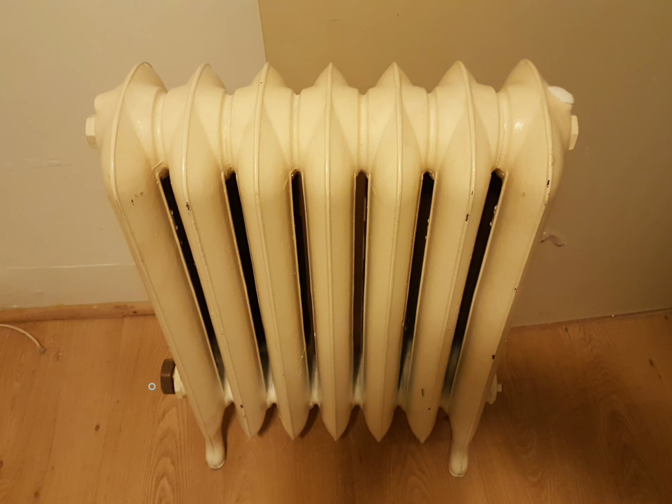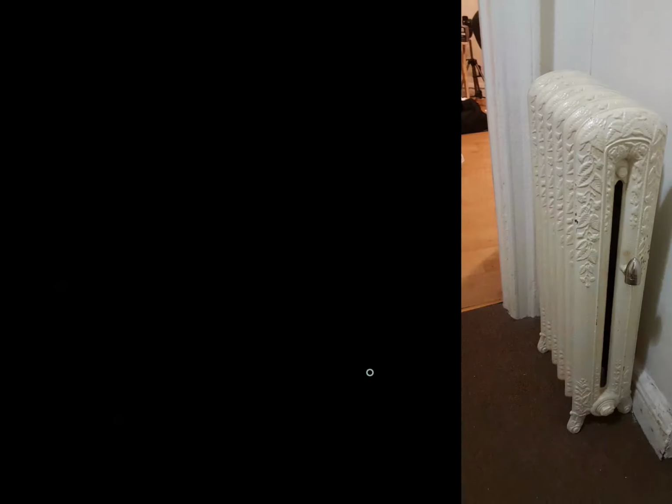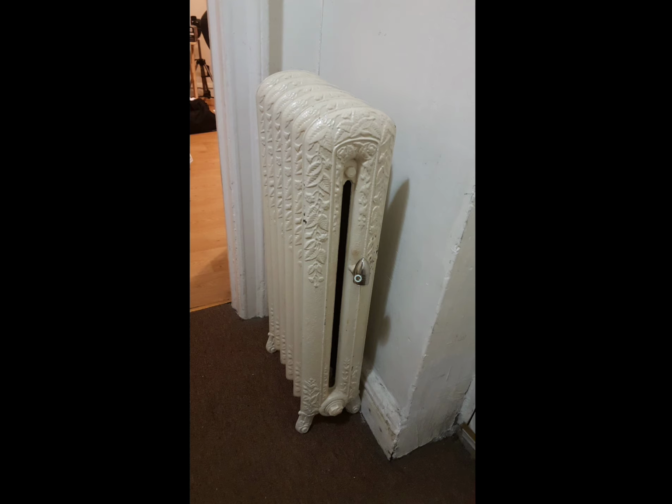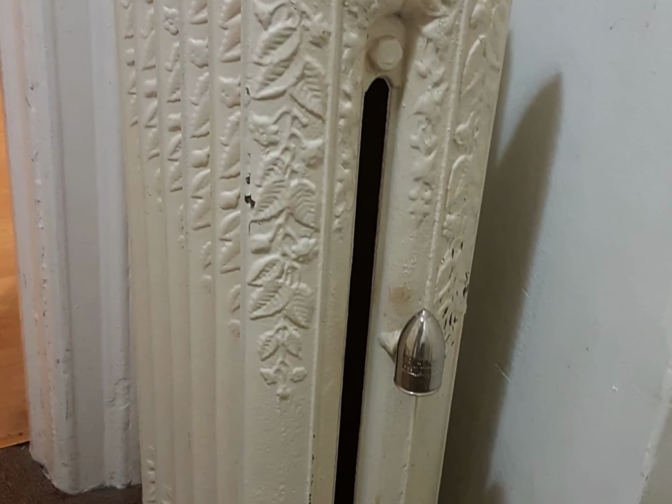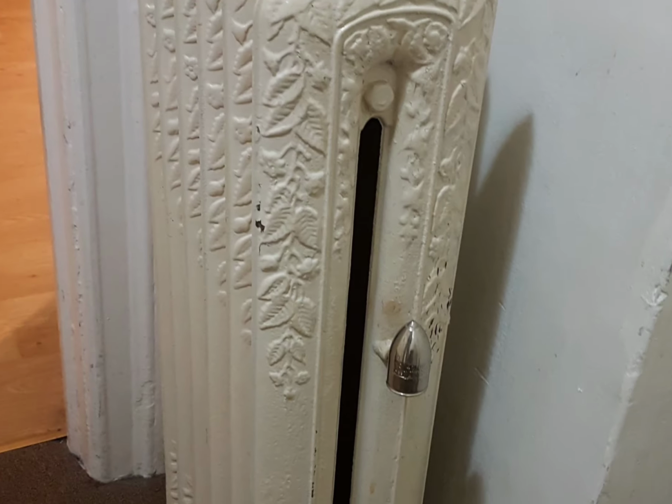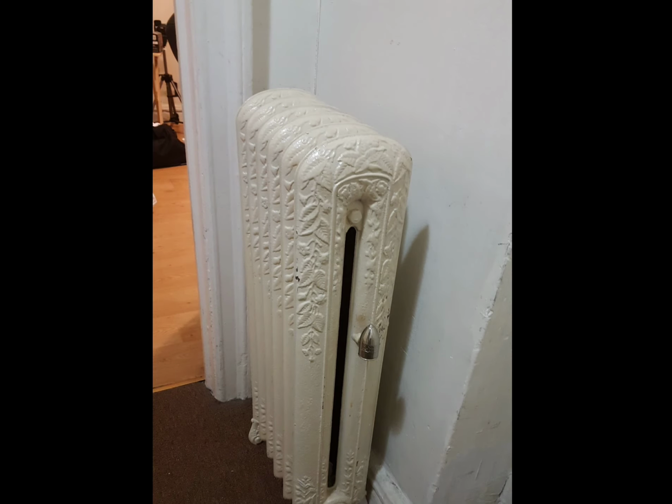On a residential, let's say you've got the small cast iron boiler. The air vent, if it's a Hoffman air vent, chances are you probably won't even hear it at all when the boiler first starts producing steam. You probably won't hear it until the steam actually gets into the vent and locks out, and then opens and locks out and does whatever it needs to do to properly vent out the radiator.